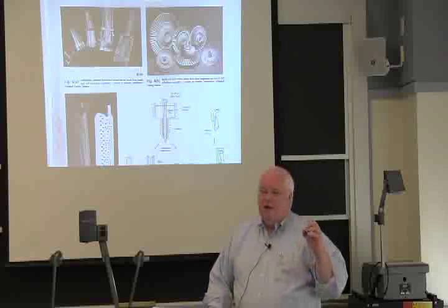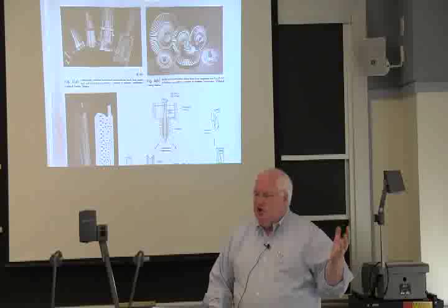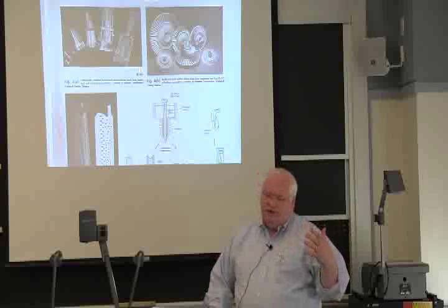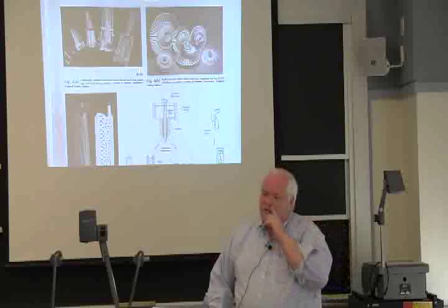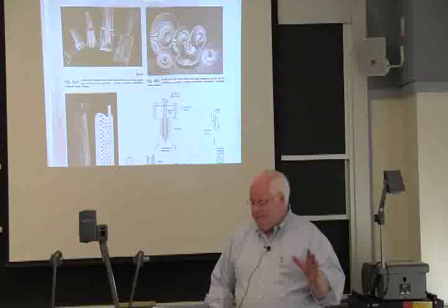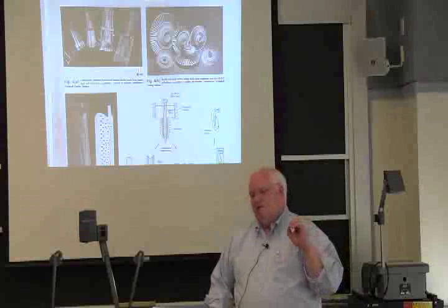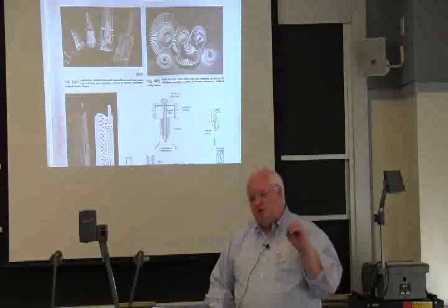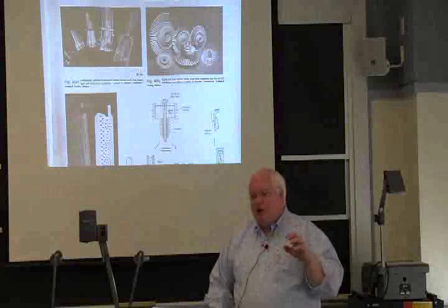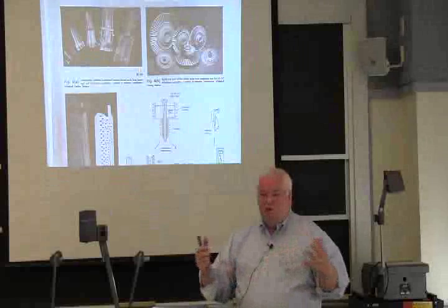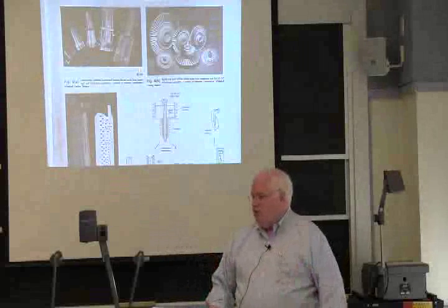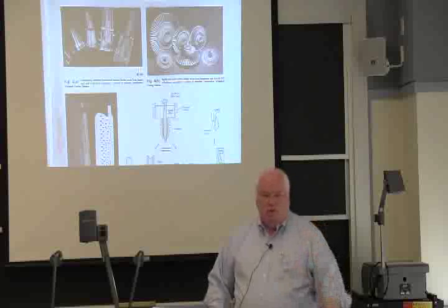And in the late 40s, the Germans had some experimental jet aircraft at the very end of World War II. But after World War II, we started building jets, and those jet engines had just polycrystalline cast turbine blades, or machined out of wrought material.